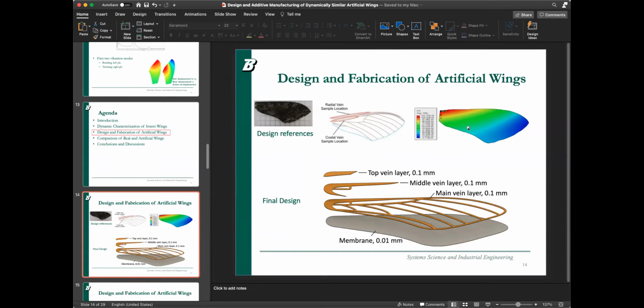However, there are also limitations, such as the resolution the printer can achieve and the smallest feature size, and also the weight. There is a very specific weight constraint for this wing, because we need a very light structure, so we cannot make more layers. But it definitely has great potential to realize heterogeneity, and this is one step we take. If in the future we get higher resolution printing capabilities, we can do that.